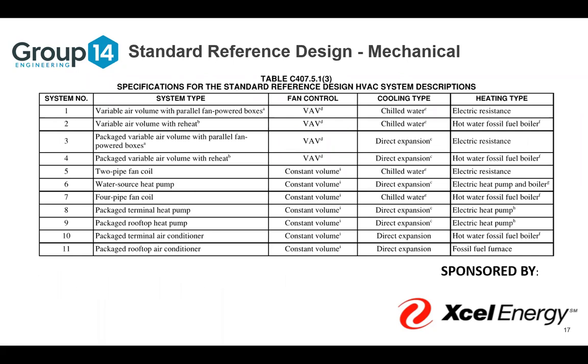The other note: we see a lot of project teams that like to consider water source heat pumps for multifamily because they can be great pieces of equipment. There's some good efficiency within those water source heat pumps, and we have a lot of clients that really like to use them in their buildings. But what's important to note here is, if you have a water source heat pump in your proposed design, you have a water source heat pump in your baseline design. And it's a lot harder to get those annual energy cost savings when you're comparing apples to apples systems.